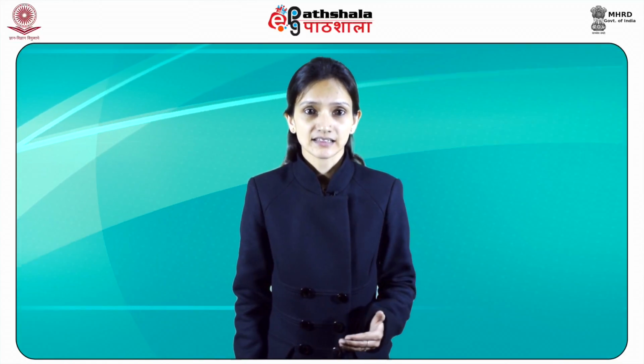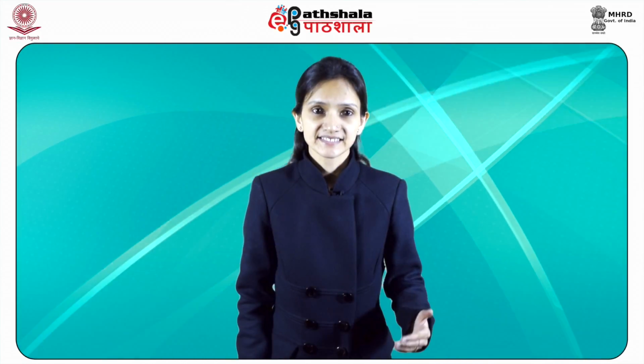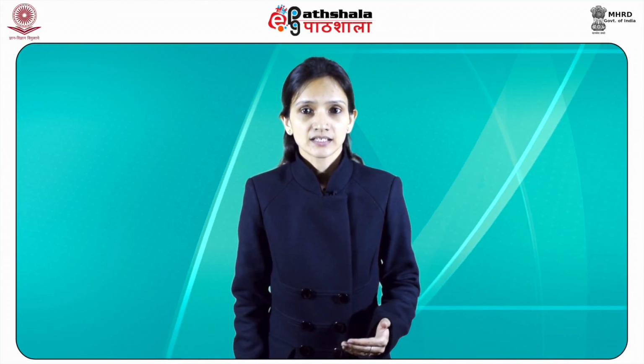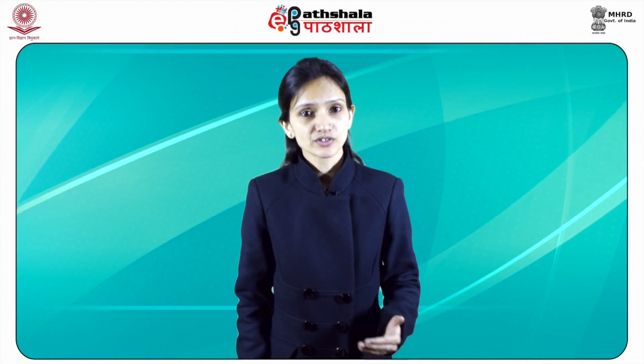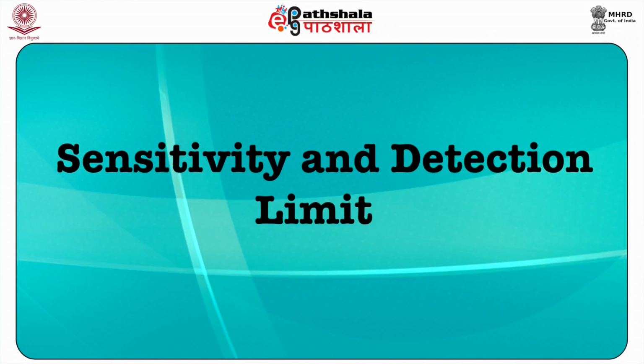Thus, higher S/N ratios are usually obtained by electronic hardware devices like filters, lock-in amplifiers, etc., or software algorithms like ensemble averaging, boxcar averaging, Fourier transformations, etc., designed to reduce the contribution of the noise or to extract the signal from the noise. Next is sensitivity and detection limit.